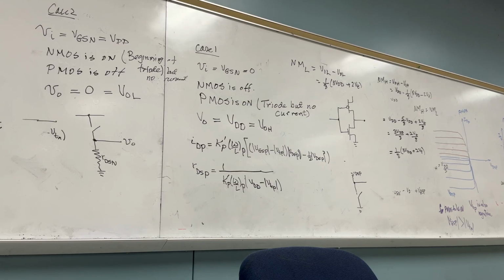Question. The higher the fan-out, remember the fan-out? What is the fan-out? How many gates are you driving? The higher it is, the higher the capacitance becomes. Why? More wires? No, capacitors in parallel. It has nothing to do with the wire; we already talked about the wires. Now, are the capacitors in parallel? Very good. The capacitors will be in parallel.